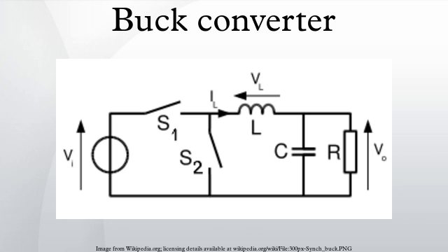Finally, power losses occur as a result of the power required to turn the switches on and off. For MOSFET switches, these losses are dominated by the gate charge, essentially the energy required to charge and discharge the capacitance of the MOSFET gate between the threshold voltage and the selected gate voltage. These switch transition losses occur primarily in the gate driver, and can be minimized by selecting MOSFETs with low gate charge, by driving the MOSFET gate to a lower voltage, or by operating at a lower frequency. Here Qg is the gate charge of the selected MOSFET, and VGS is the peak gate source voltage.